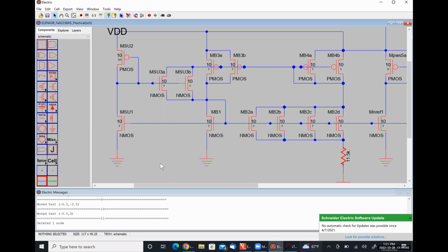differential amplifier stage, which should go relatively quickly because it's only 6-ish transistors. So we might have a review-ish thing about the operation of the single stage op amp, which is what we're going to be using as our differential stage, because we want differential input, single-ended output. So why beat around the bush and just go for it since we're running low on time. So we'll review very basically the large signal and small signal operation, just so we know what our expected operating points and stuff like that will be.